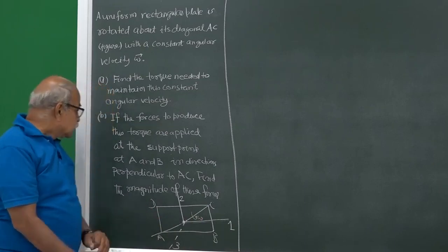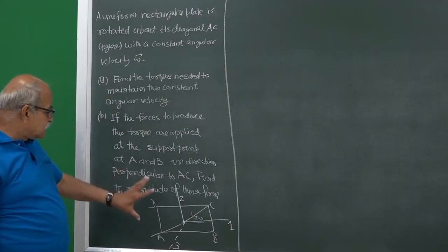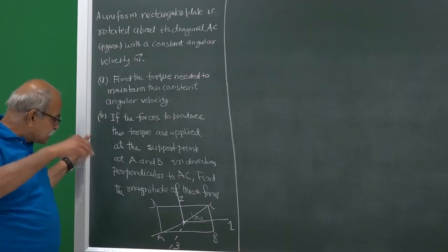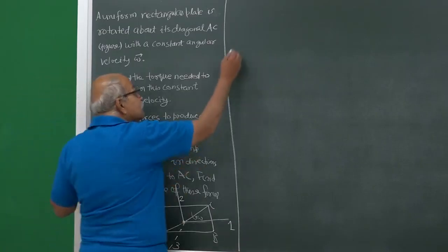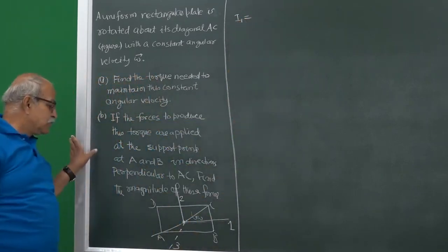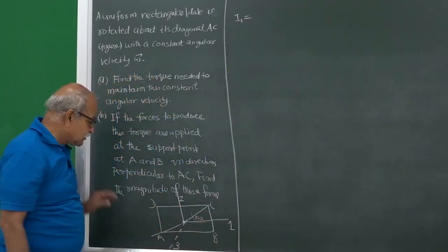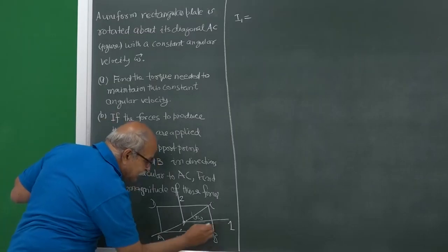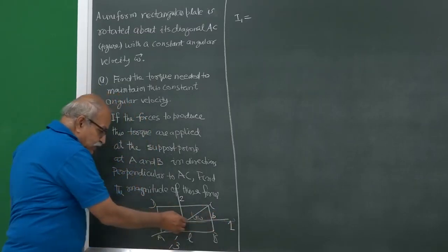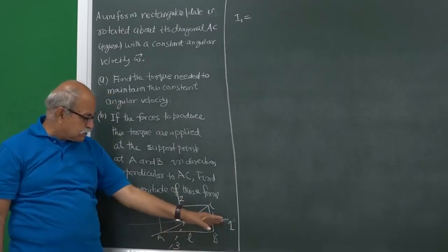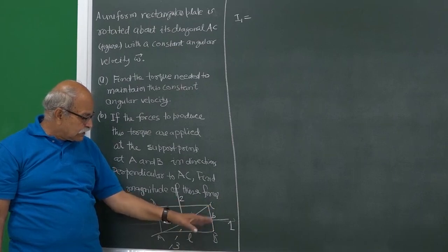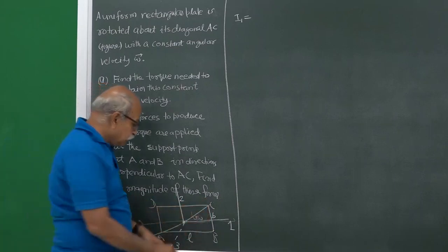Okay. So, I am using these 1, 2, 3 axes, which are principal axes. So, I can write what is I1? I1 is the usual moment of inertia about the first axis. Let us take length as L and width as b. So, the moment of inertia of this plate about this line will be m b square by 12, where m is the mass of this plate.